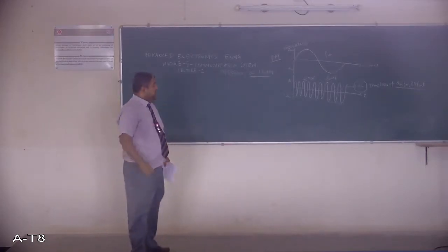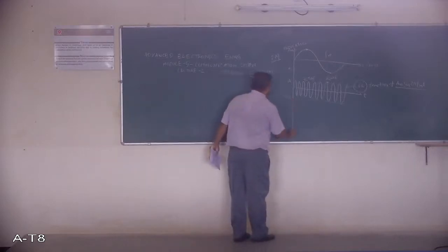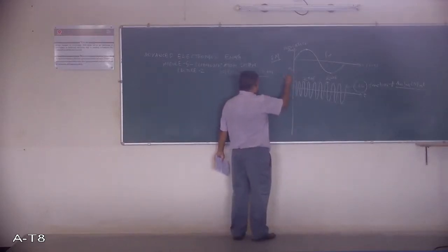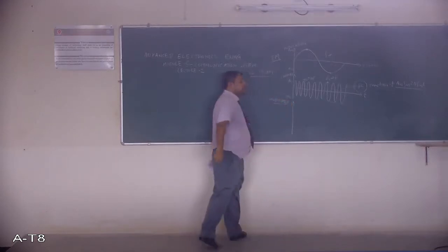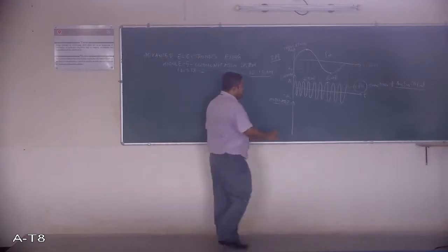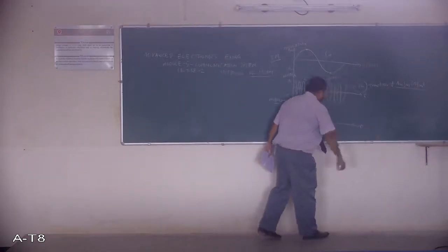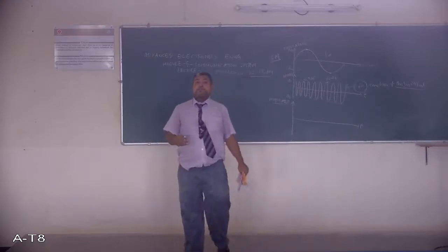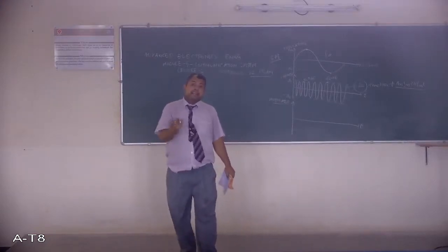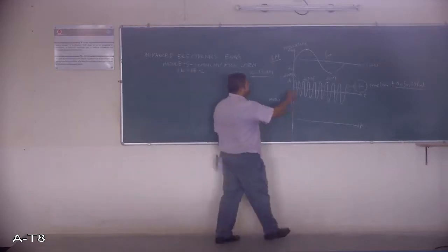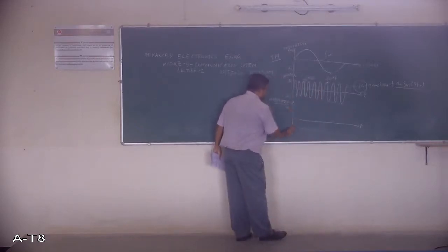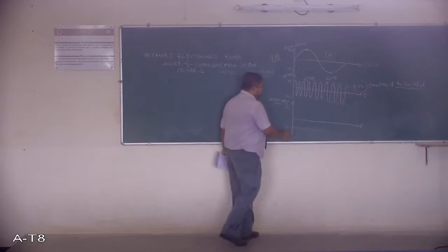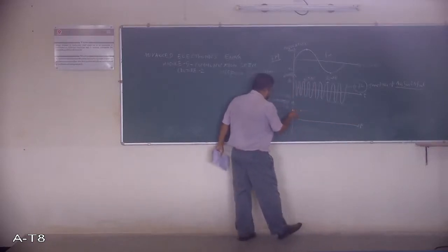That means in case of frequency modulated waveform, so this is modulating signal, this is carrier signal, which is a high frequency signal. Below I will draw, this is modulated signal. So in case of frequency modulation, what we will see is this modulated waveform will be a function of frequency and variable function of frequency, and that change in frequency will be caused by amplitude of the modulating signal. That means this FC, AC and AC amplitude will remain same. This is AC and minus AC. There will be no change in that. So amplitude, there will be no change.